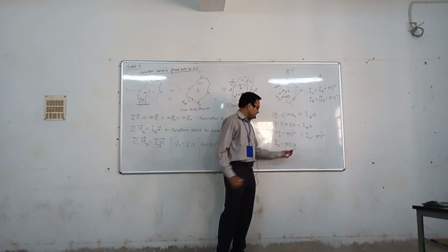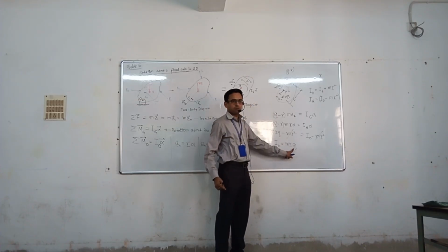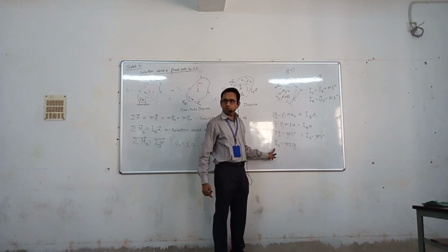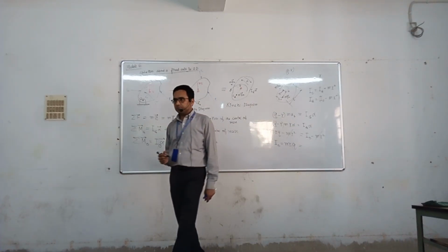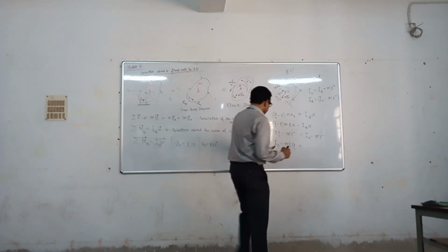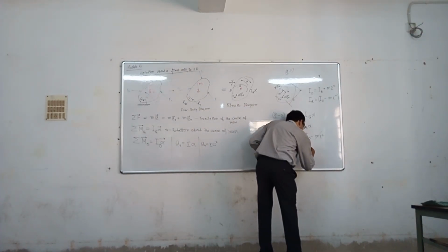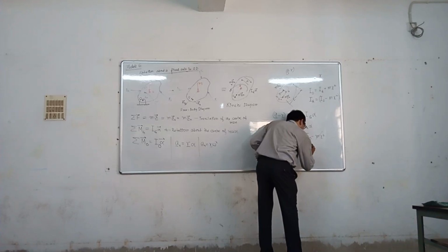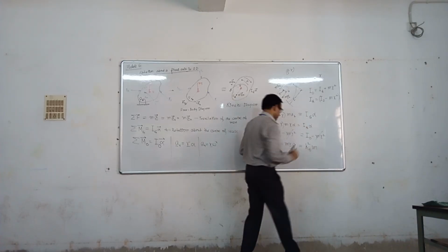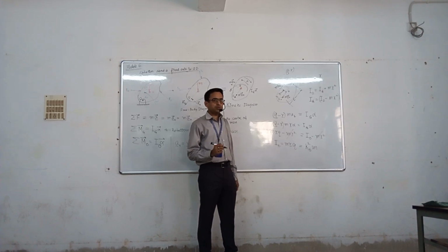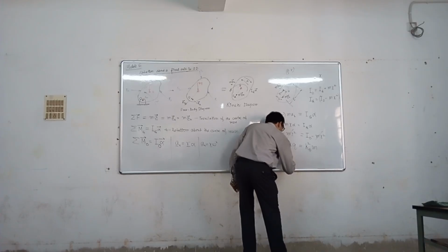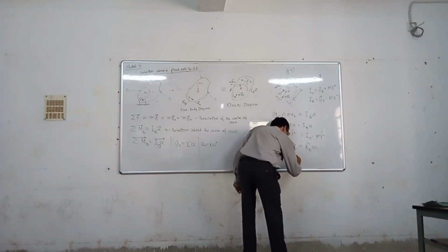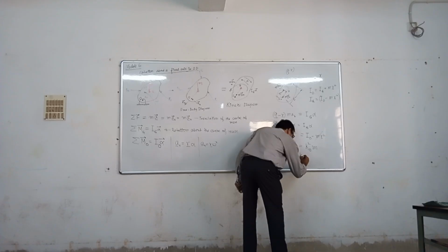Again, you see that here only q is unknown. Right? Again, from the definition of radius of gyration, I can write that IO is equal to M K square. Therefore, I can write that q is equal to K0 square by r bar.